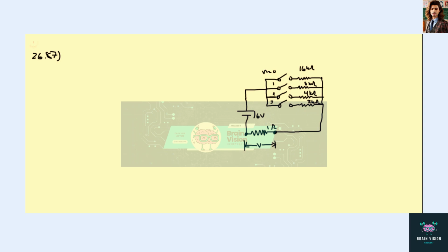So we have a circuit here, and it says it's a primitive 4-bit digital to analog converter, or DAC. In this circuit, to represent each digit, 2 to the n, of a binary number, a 1 as the nth switch closed, whereas 0 as the switch open. So for example, 0010 is represented by n equals 1 closed, while all other switches are open.